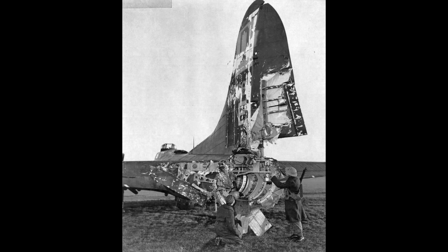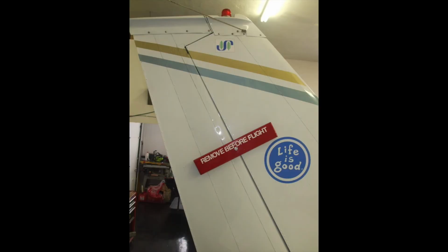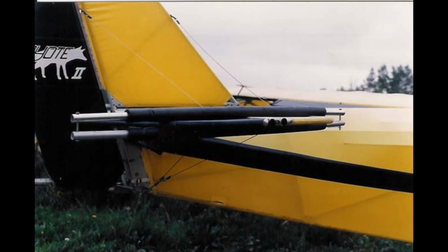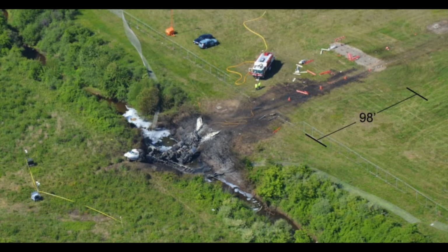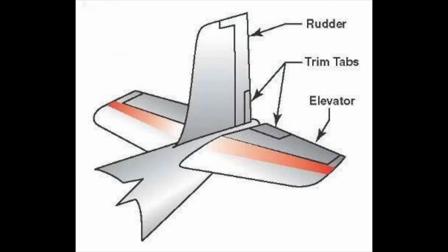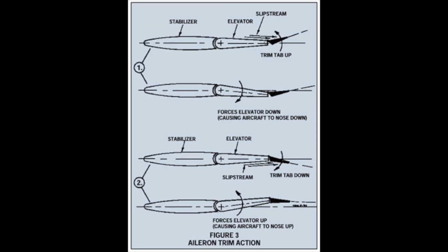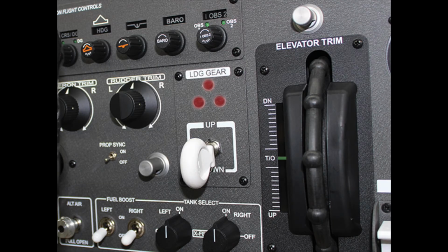Small planes often have rudder locks and elevator locks, known as gust locks, to avoid damage from strong winds when the aircraft are parked. Woe is the pilot who takes off without removing these before flight. A further refinement has been the fitting of trim tabs to rudders and elevators. These are small control surfaces employed to apply a force by using the slipstream. Trim is set in the cockpit and lessens the effort needed to move the rudder pedals or control column.